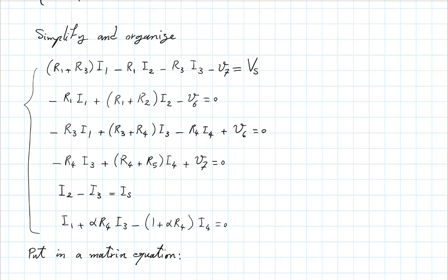So here's a simple example. If you have a circuit that has a couple of nodes and many elements connected between them, so you have many, many meshes but only a couple of nodes, would you use mesh analysis or nodal analysis if you had the choice?